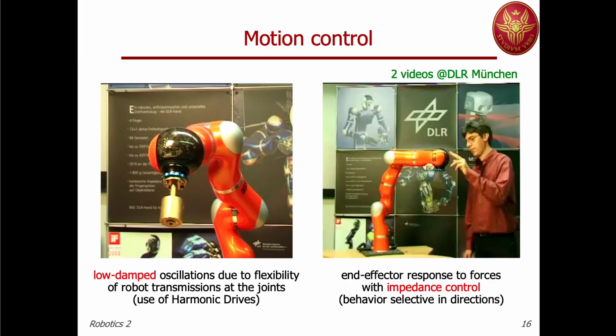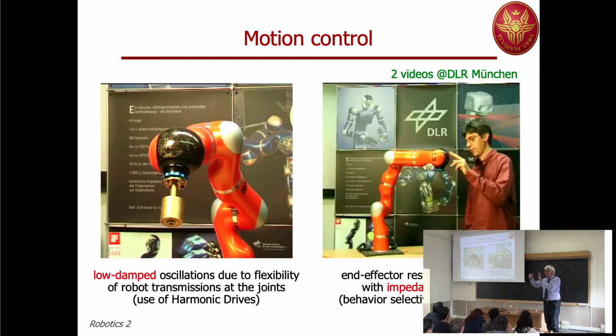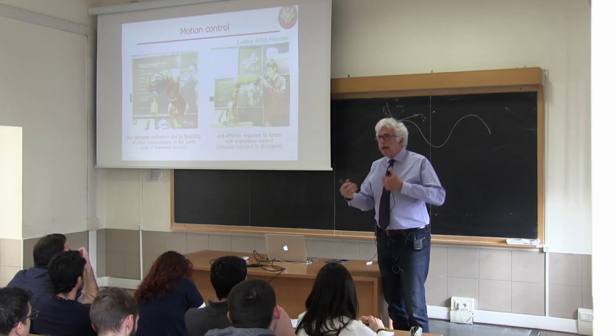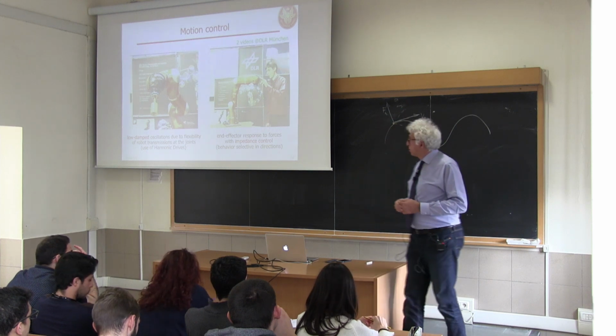Okay? And the vibration is just because you have fixed one part, the motor, you have some elasticity, let's say a spring, and you're pushing another mass at the end effector level, and what you see is not the motion of the motor, which stays fixed, but the oscillation due to the compliance of the transmission. Okay? So this is good and bad, again. Sometimes you introduce intentionally compliance if you're able to control this vibration so that the system may absorb energy, especially if it goes in contact.